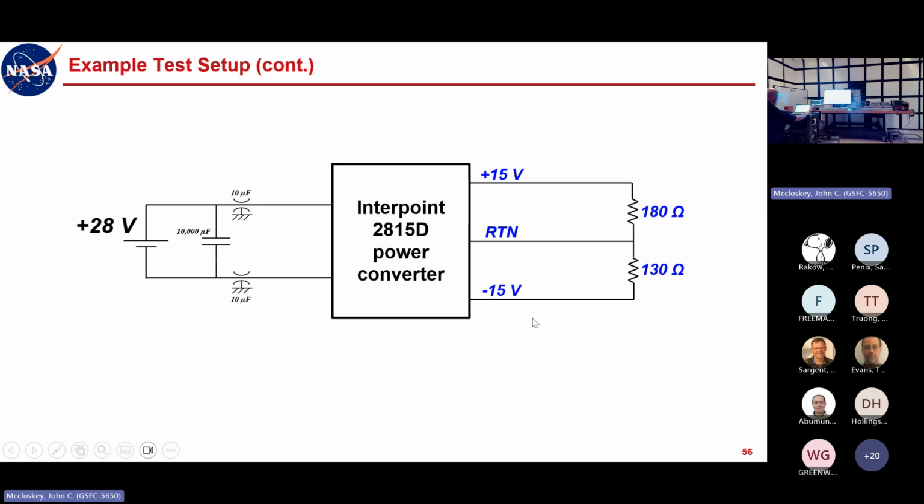It's the capacitance that is allowing any common mode current at all to flow. At DC, there's no current, right? The DC current's not going to flow through capacitance, but as soon as you get up to 400 kilohertz, that capacitance is going to have at least a low enough impedance to allow some of that AC current to flow. Yeah, but we know what the common mode is.